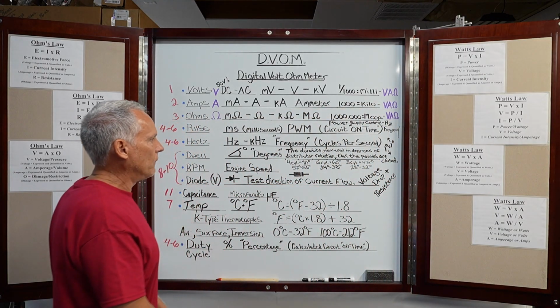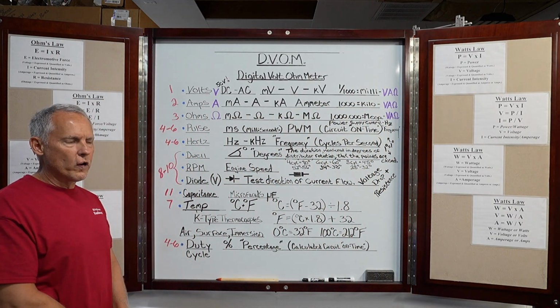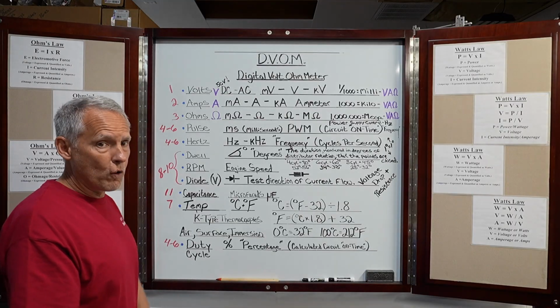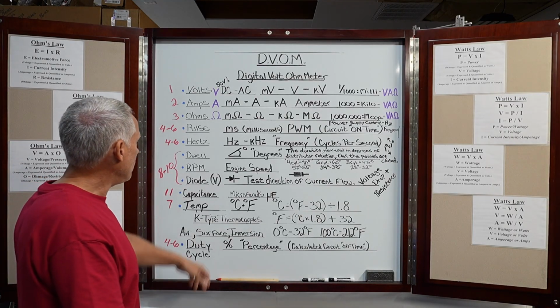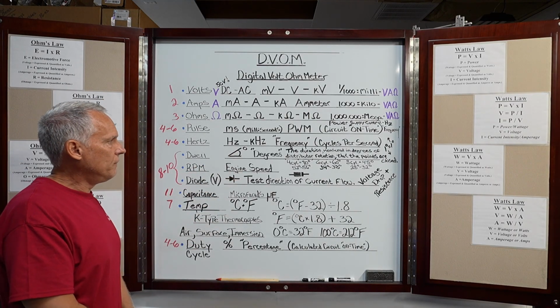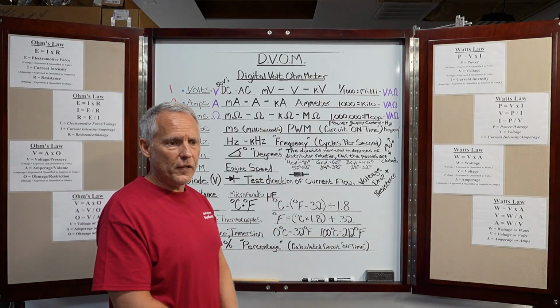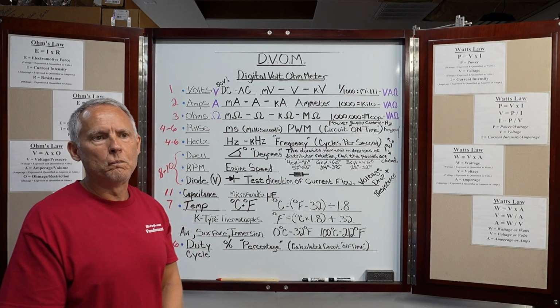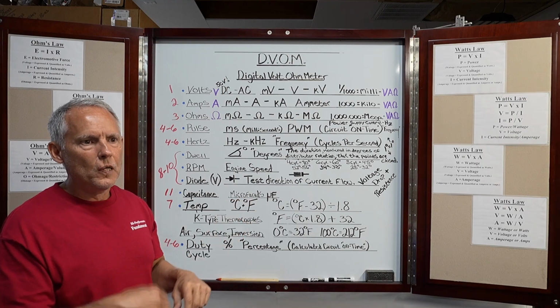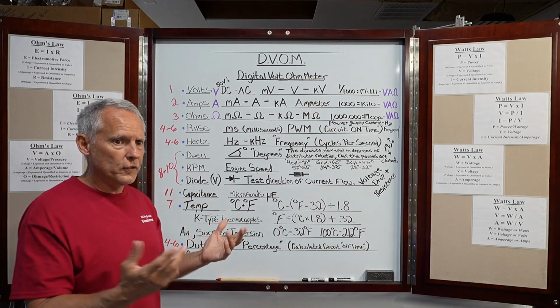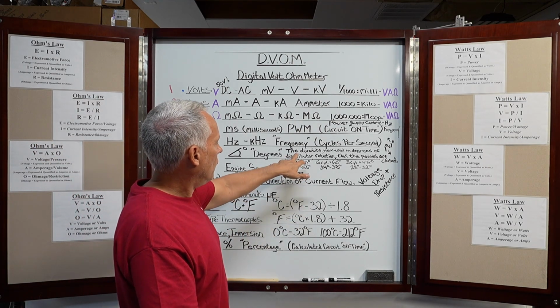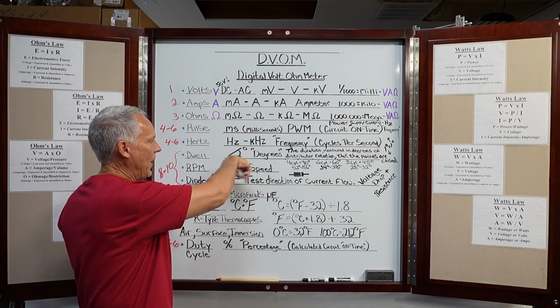For the older guys out there, the guys who still work on the old cars or have been working on cars for a long time, or motorcycles too, as a matter of fact: dwell. Back in the day, what is dwell? Well, it's a measurement of degrees, and we used it back then for setting points. A points-condenser system, single points, dual points. You set the dwell. So what is dwell? Like I said, it's a measurement of angularity.